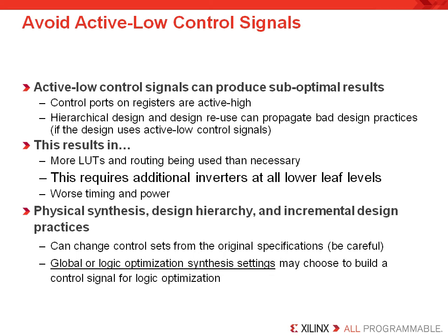Active low signals use more LUTs because they require inversion before they can directly drive the control port of a flip-flop. This inversion must be done with the LUT and thus takes up a LUT input. Likewise, because only a single reset can be brought to the register, if the remaining logic to be grouped does not share all common control signals, it cannot be grouped into the same slice.